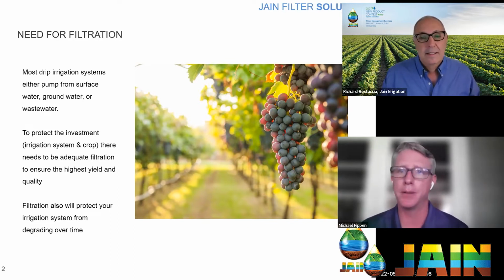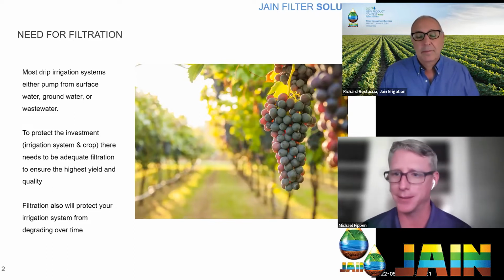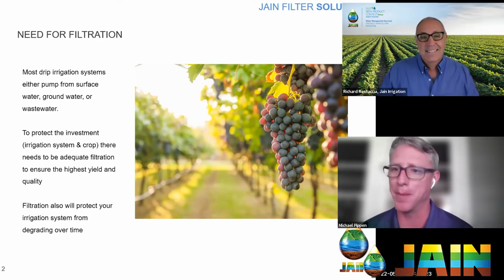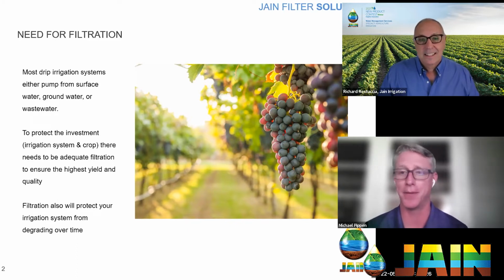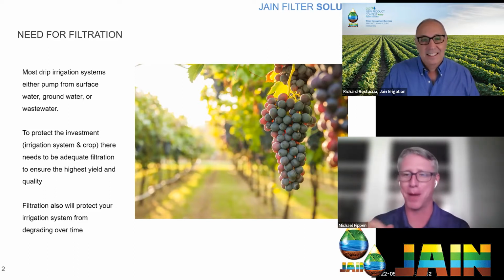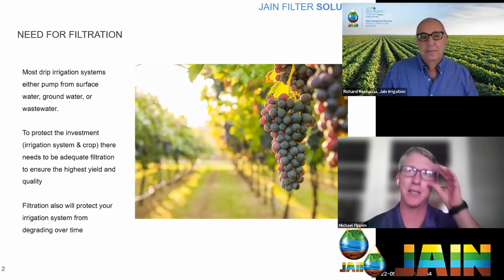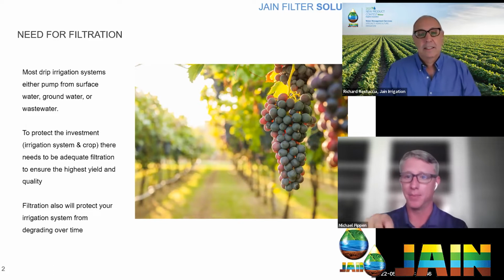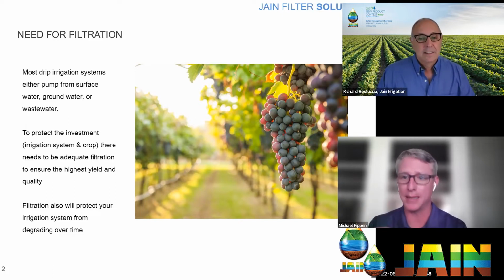But what happens if your line gets broken when they bury the new fiber optics cable in your yard, like happened in my yard the other two days, and I didn't have a filter on one of my zones, and so for 2 days I cleaned sand out of my nozzles. Every time they'd pop up, you'd clean one, and then go to the next one. If we had a small filter on there, I would be cleaning one filter versus a whole bunch of nozzles. And in some cases, I had to take some of my pop-up heads apart, wash them, and put them back together.